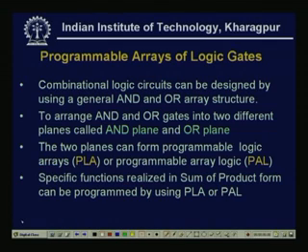So far we have read that all combinational logic can be realized by a set of functions, where the functions are represented in sum of product form. Now, what does this sum of product form mean? Sum means our OR gate and product means the AND gate. So, mainly it is an AND-OR realization. Now, from one circuit to another circuit, this AND-OR combination will differ.